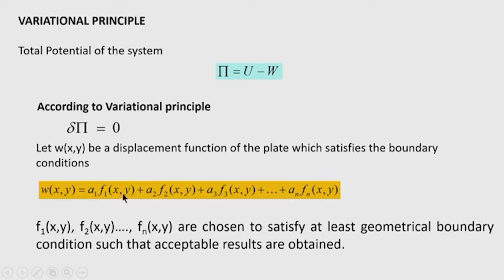In some cases, for example, in simply supported cases, if we take the series as a double Fourier series, that is the Navier series, double trigonometrical series, then the first term will give a very accurate result for the deflected surface, and a higher number of terms are required to improve the accuracy in the bending moment and shearing force expressions.